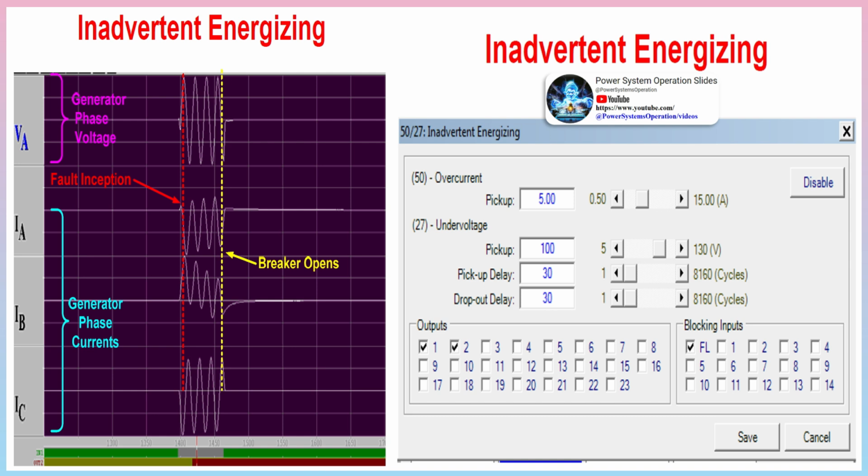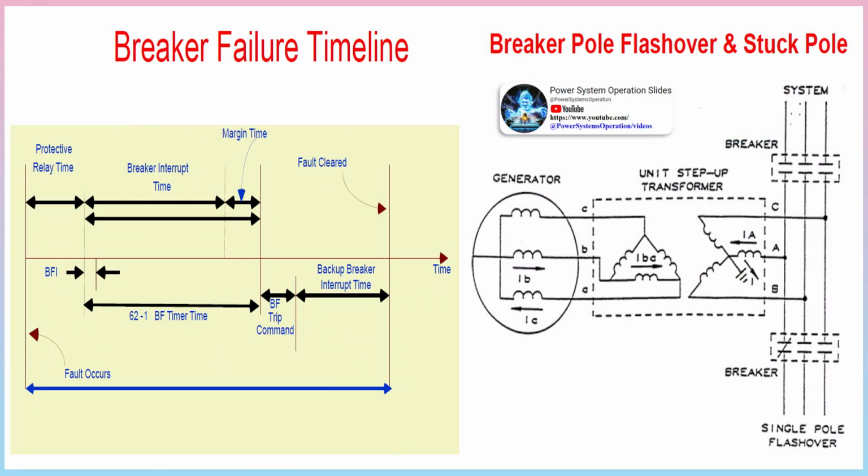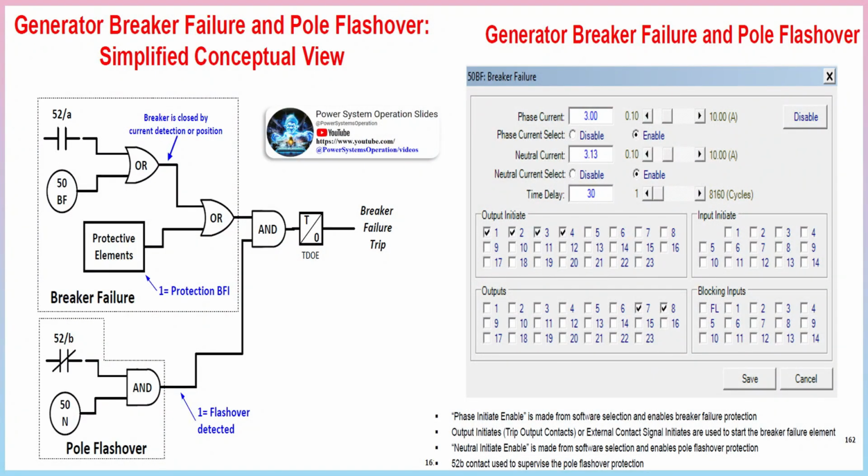Overspeed protection. While it is the general practice to provide mechanical overspeed devices on both steam and hydro turbines, which operate directly on the steam throttle valve or main stop valve, it is not usual to back up these devices by an overspeed relay on steam-driven sets. It is, however, considered good practice on hydroelectric units, as the response of the governor is comparatively slow and the set is more prone to overspeed. The relay, when fitted, is usually supplied from the permanent magnet generator used for the control of the governor.